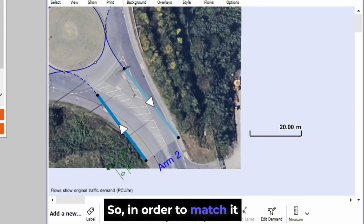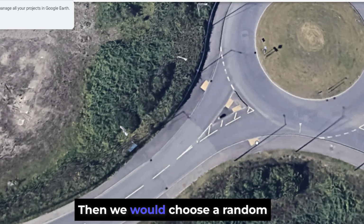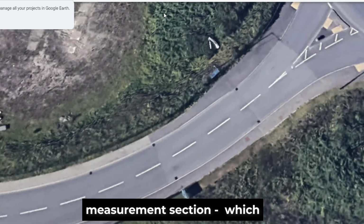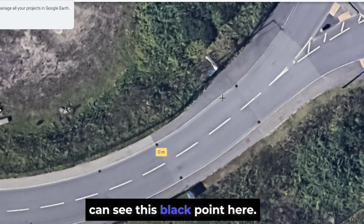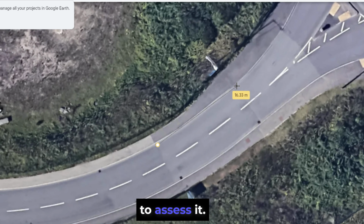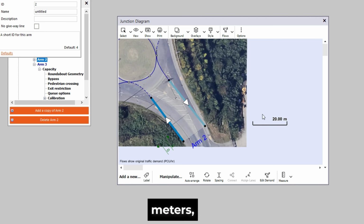So in order to match it to the actual layout, we would go back to Google Earth. Then we would choose a random measurement section, which will be easier to measure. We would measure, for example, I can see these black points here, so it would be easier to assess it. And that is, as you can see, 16 meters, 0.3 or 0.4.